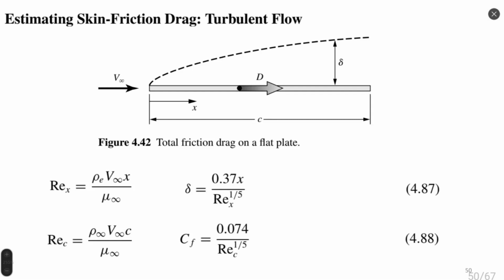Thickness of boundary layer is also proportional to coordinate, as we saw in the previous case. So it will increase with increase of coordinate. And Reynolds in power 1/5 is not increasing so fast as the coordinate.